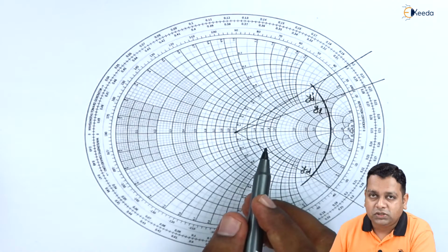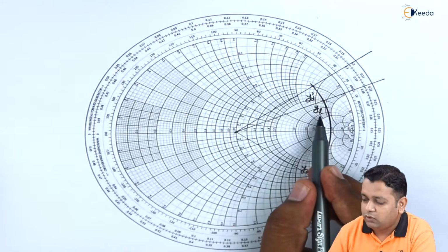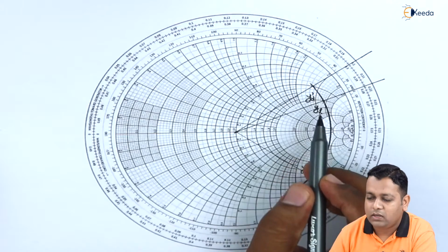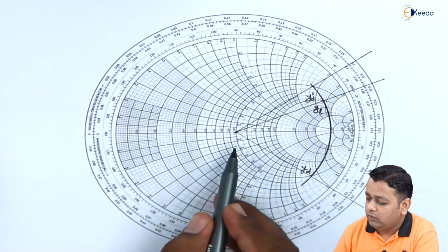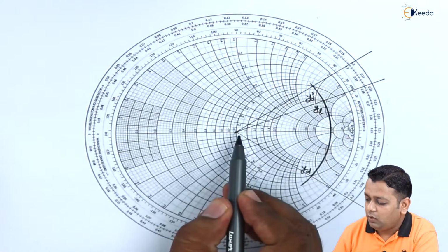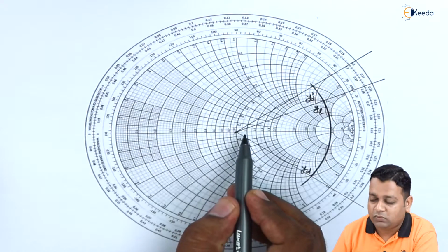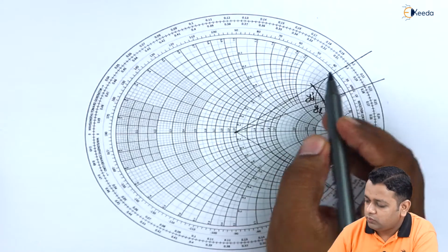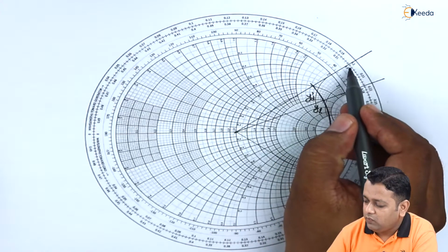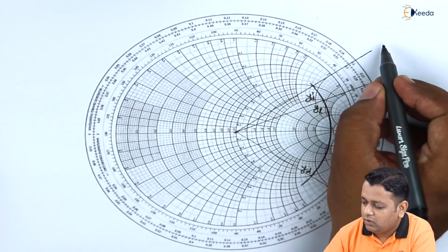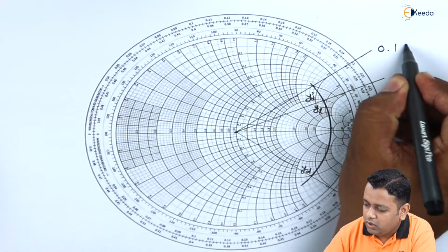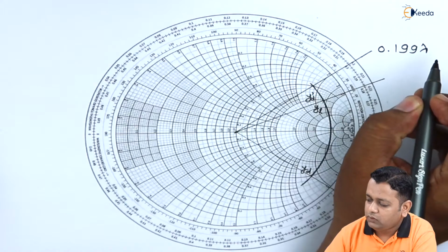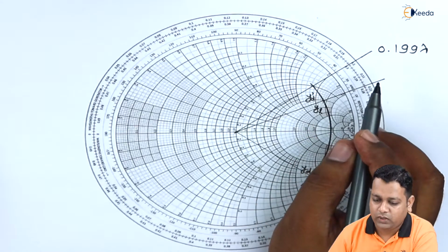So on the Smith chart, we have the marking corresponding to the YL here. We have YD also and YD dash also. Now when we cut these by joining with respect to the center of the Smith chart, we have the scale markings correspondingly. So for YD dash, we have here the value 0.199 in terms of multiplicand with the lambda here.